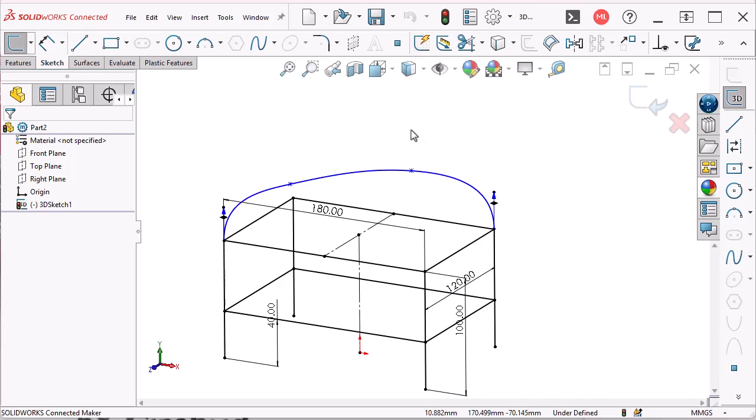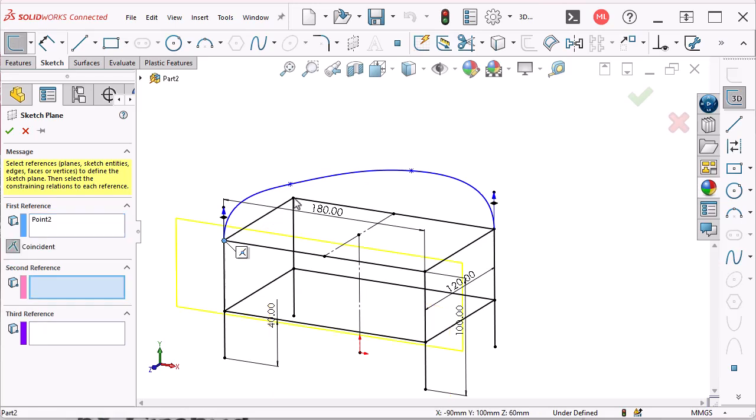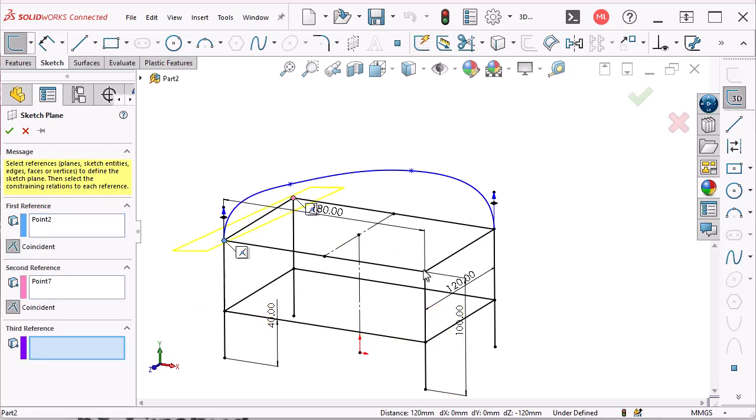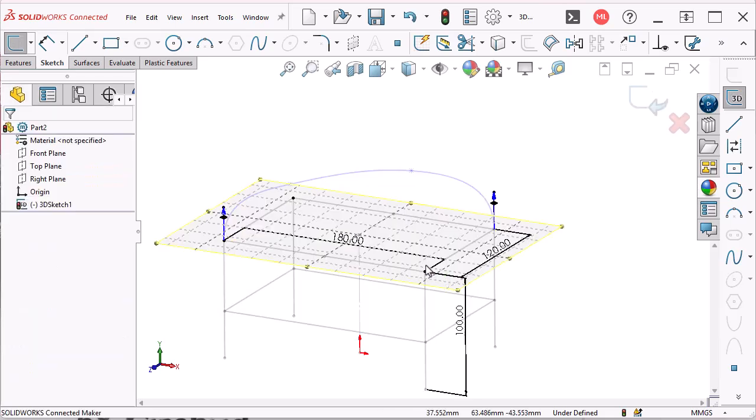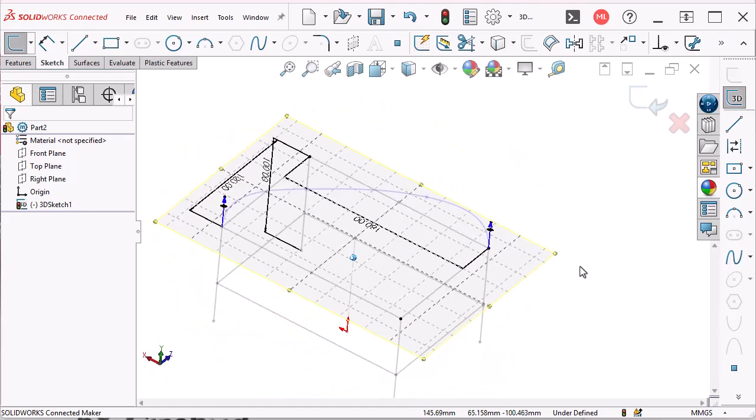And one of these is the plane that goes into a 3D sketch. This is different from the plane that's in a 2D sketch, and it works much differently. So we can click on the plane. I want to put it on the top surface, so we'll just click 3 points here. 3 points make a plane, and right click to accept that. Now the plane is shaded and it's showing a grid. Don't freak out, okay? Nobody's going to tell your mother that you're drawing with a grid.